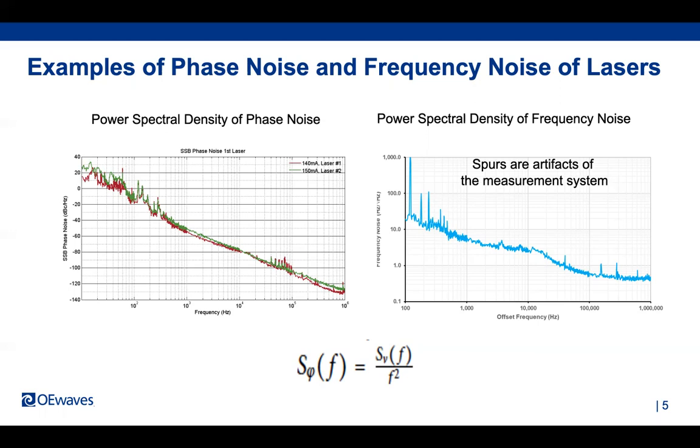Typically people increase the noise of the laser in order to suppress the shot noise. But it turns out that if RIN is present, that's going to keep the laser from operating at the shot noise limit. And that's an important piece of information that can impact the performance of a variety of applications, such as, for example, frequency modulated LIDAR.